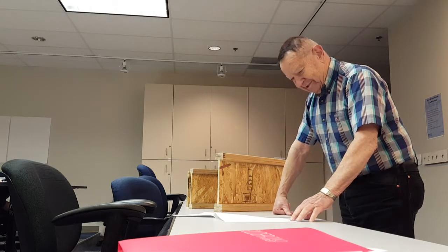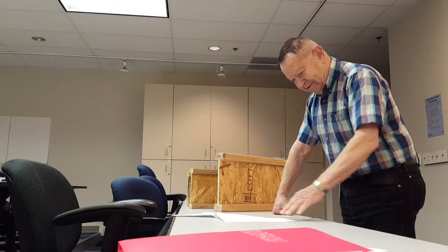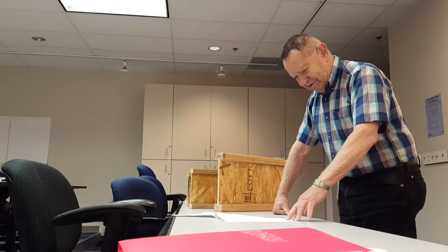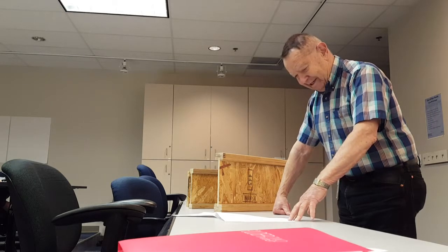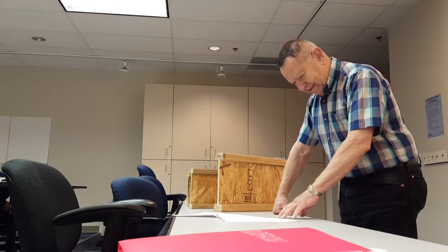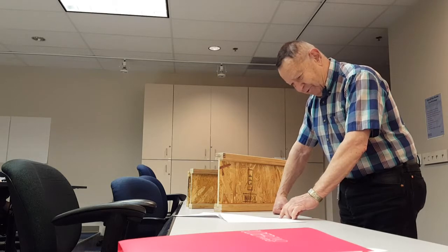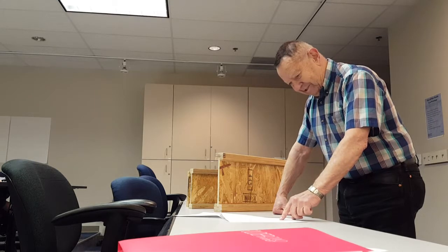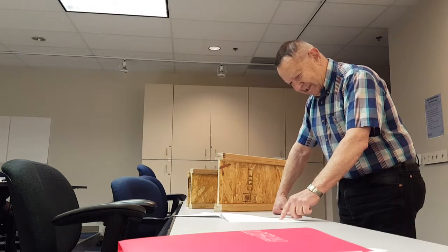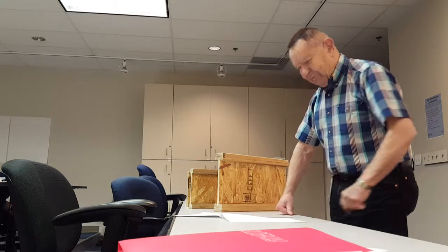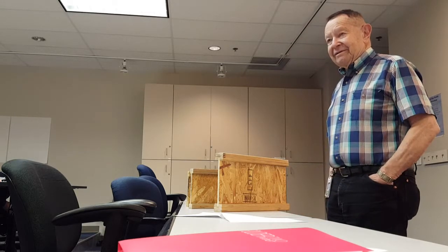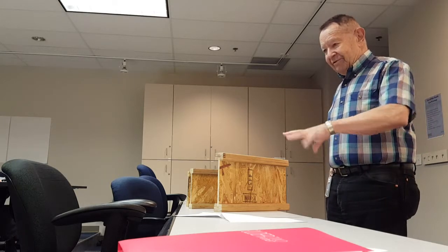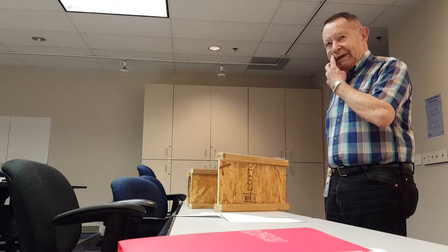And so that's the same 3/2 width, and supposing it's the same density. And then you do your integral 0 to 19.5 y², and you're comparing 428 and change for that with the 237 and change from the truss. So it is more, but it isn't that much more, considering the difference in cost and weight and so on.